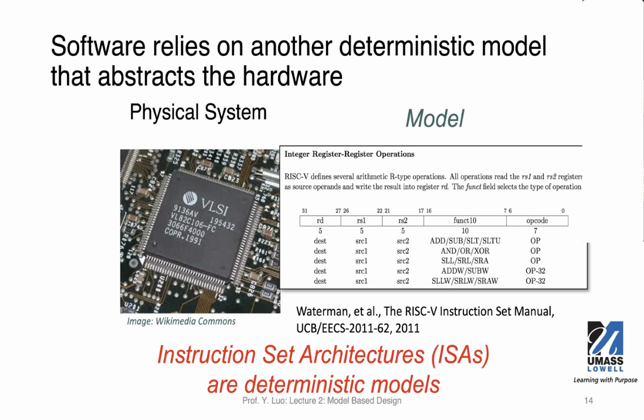Those two are, I would say, probably the most popular instruction sets for the majority of processors. In this example, it's a RISC-based instruction set. The reason we call it RISC is because every instruction has the same 32-bit length as shown here. On the higher bits, it defines the locations of the registers.